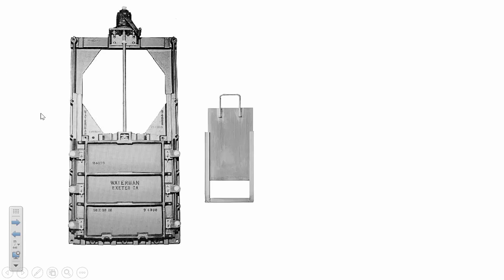And when they get that large, the other issue is that the hydraulic pressure pressing them up against the frame is enough that the friction inside of the frame is a really important issue of how easily it can be lifted. So the force that you require to open the gate isn't just the weight of the gate, but it's also related to how hard the water is pushing up against the frame.